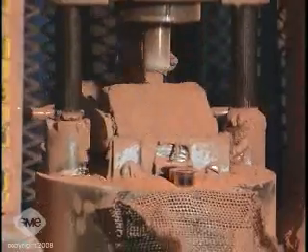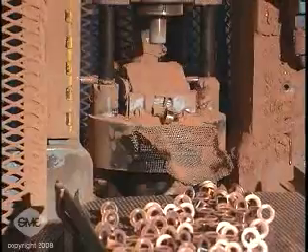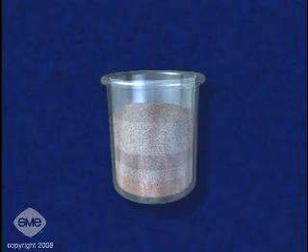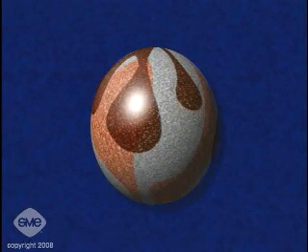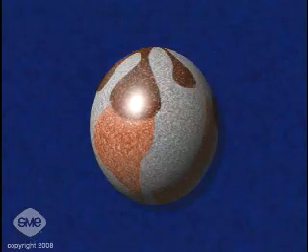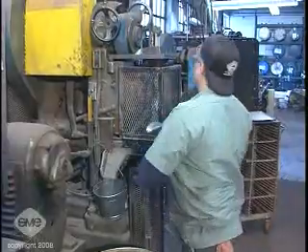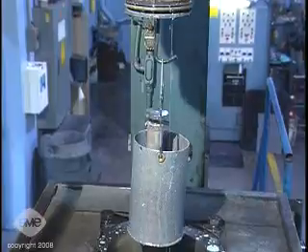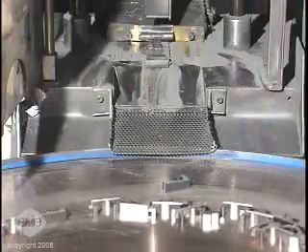Metal powders used for parts production can be a combination of various elemental particles or pre-alloyed powder. If elemental powder is used, each of the ingredients that will comprise the desired part are mixed in proper proportion into a uniform blend. With pre-alloyed powder, the proper proportion of ingredients is already present in each particle. In either case, additives such as binders and lubricants are usually added. The powder is then consolidated in molds or dies, shaping and densifying it into a compact of the desired part.